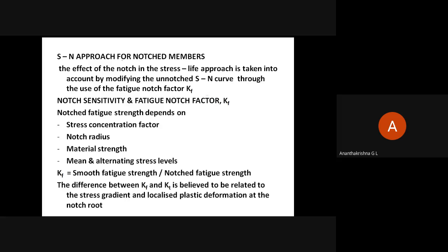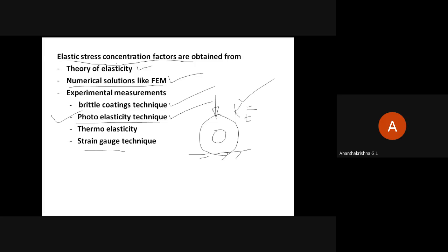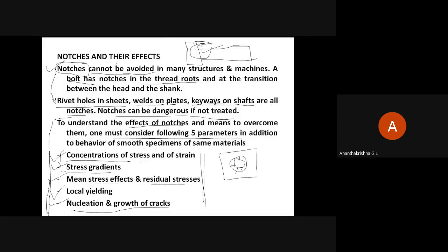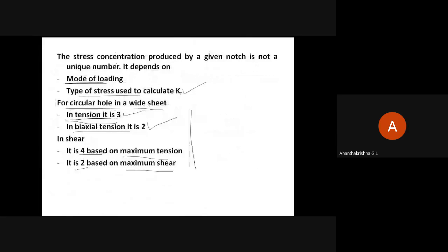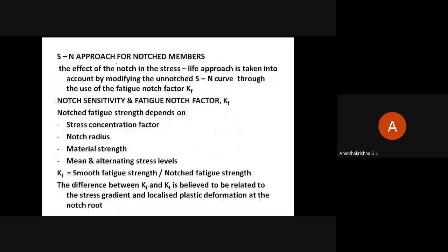Next, the S-N approach for notched members is the next topic. Let's look at the stress versus number of cycles approach for notched members. Notch can be a hole, groove, keyway, stepped shaft, or whatever. Any geometrical discontinuity, they term it as a notch. Please remember that.